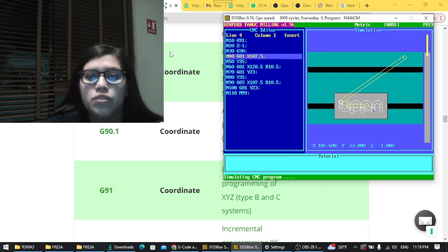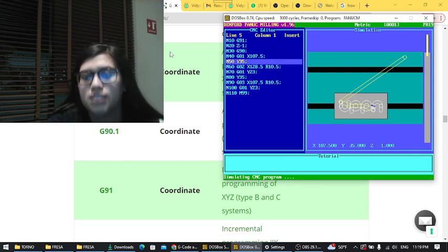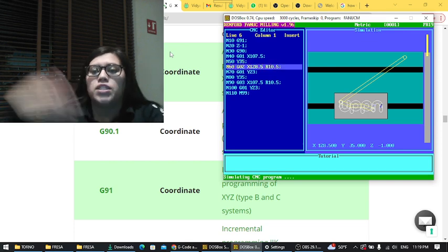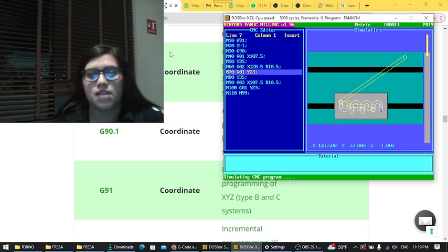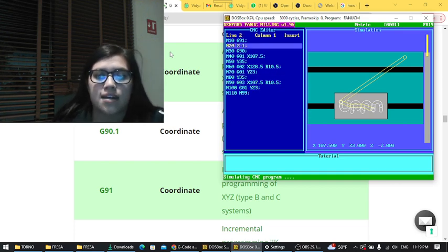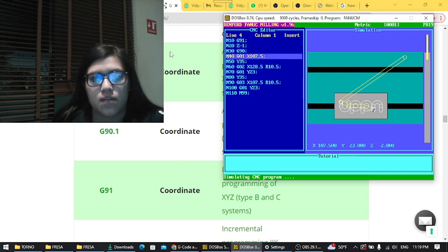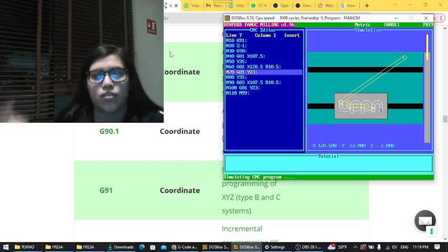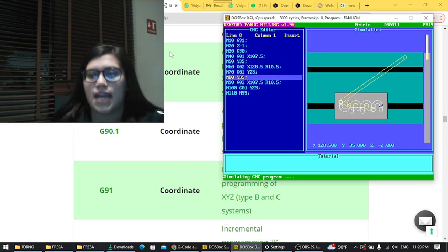It actually moves to X28.5, which is going to be the starting point to the end point with a radius of 10.5. So just defining that arc, and we have the counterclockwise and clockwise orders. It ends with the counterclockwise, it just returns back and forth. That's all it has to do.